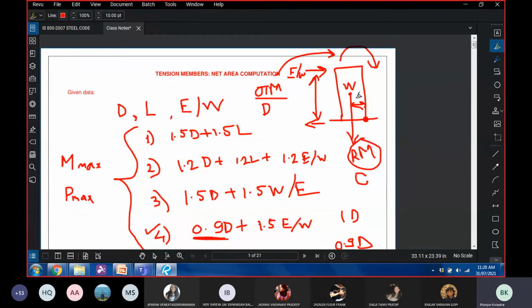So this weight times whatever this lever arm is your resisting moment, right? So your resisting moment is a function of the self-weight of the building. Now you don't want to overestimate your resisting moment. We always underestimate our capacity and overestimate our loads. If you say that 1.5 times dead load is resisting my overturning moment, then you might be incorrect. You may not have 1.5 times dead load that is resisting your moment.